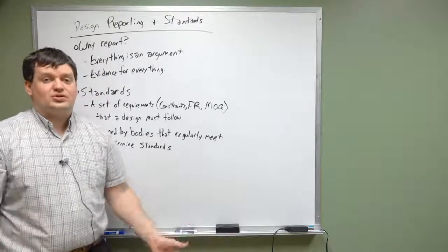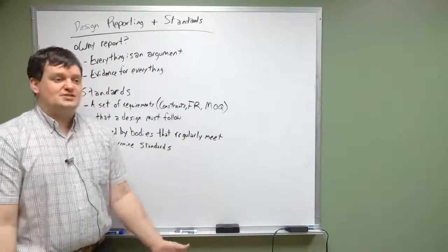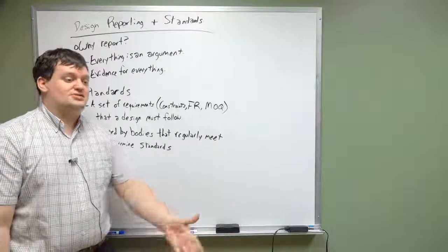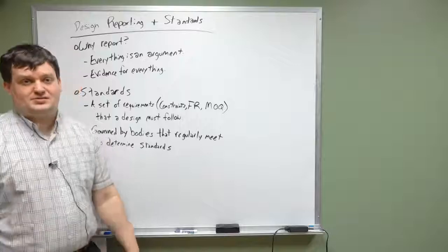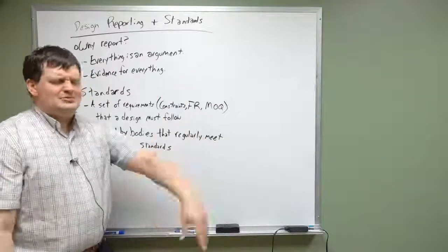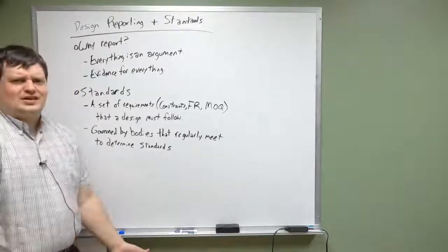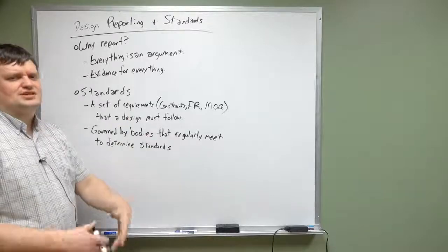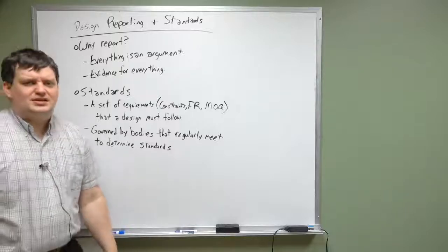That's the beauty of standardized components, though. They sell them in bulk, they manufacture them in bulk, and you figure out how to use them. If you need something better, you find something better. You find a distributor of something better. You know, instead of grade 5, you get grade 8. It has better strength properties, better hardness properties, made out of nickel chromium, made out of a different type of steel. You can get those, and they're standardized. They follow a very standard set of regulations as far as how they're made. Okay, and that's the goal of standards.